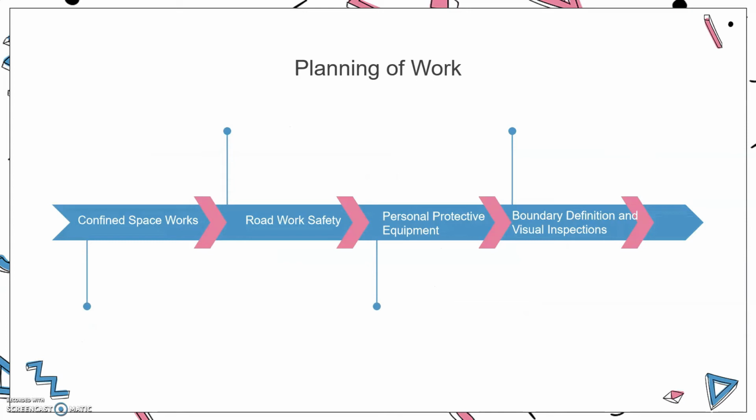When working on the carriageways, temporary traffic arrangements will be coordinated in accordance with the Code of Practice for signing and guarding as issued by the Highways Department. PPE such as safety helmet, harness, shoes, and goggles will always be provided. Staff will take necessary precautions and utilize them when potential hazards are identified. An emergency telephone list will be provided for the team leader to make sure that the utility companies, police department, and fire department can be contacted should the need arise.